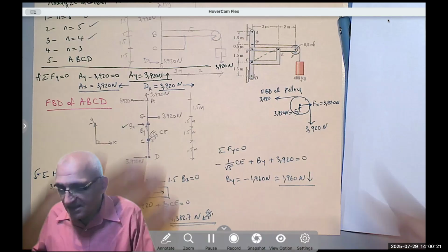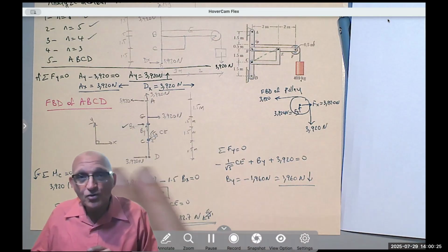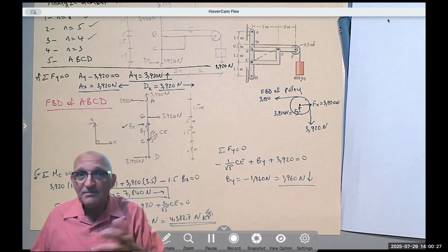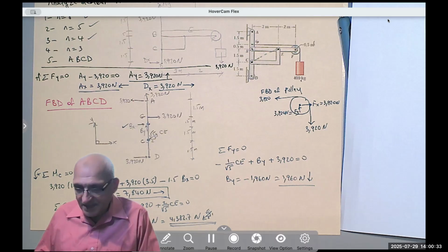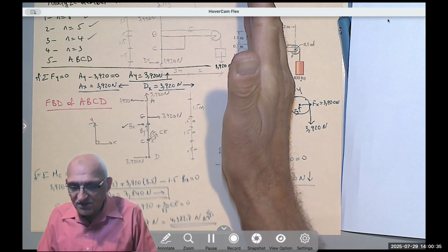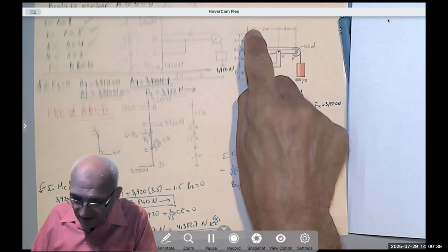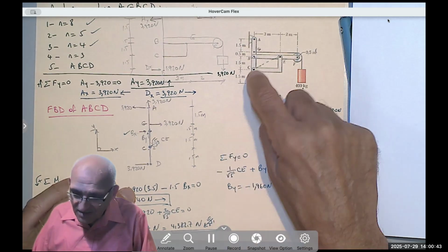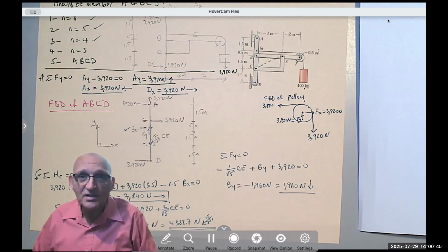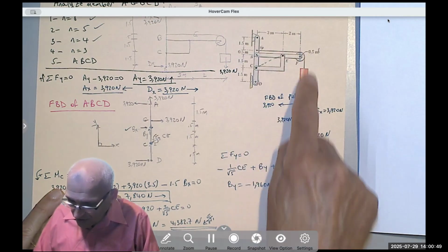If you see that you can find some of the unknowns from another member, be my guest and analyze that member. But generally speaking, it was easy just to concentrate on the member we have and say, okay, I can find these three reactions. The 8 becomes 5. This is a two force member, so I subtract 1. Now they are only really 4. This thing is going all the way here.